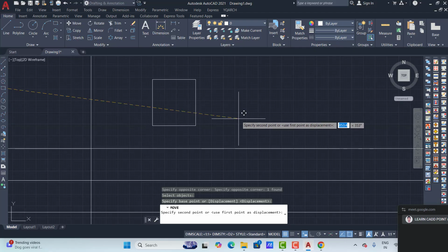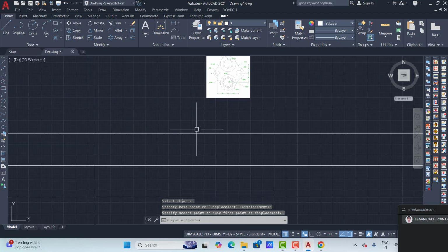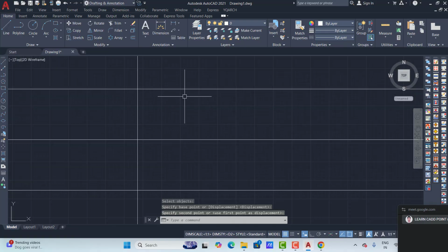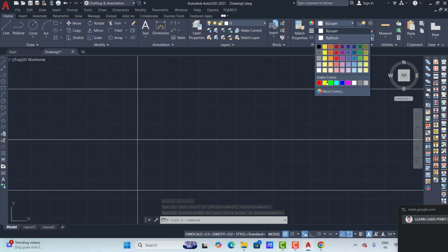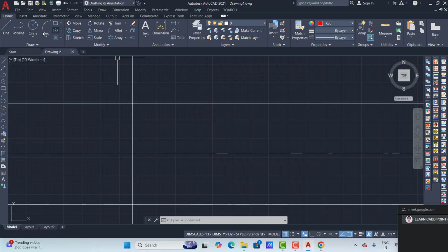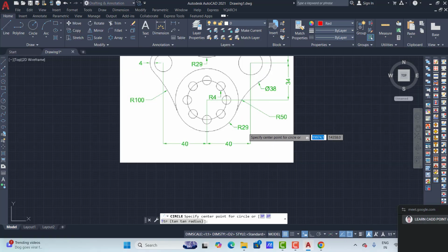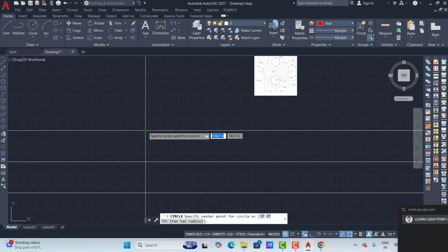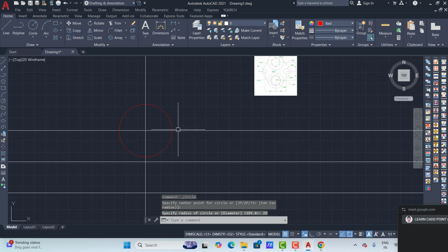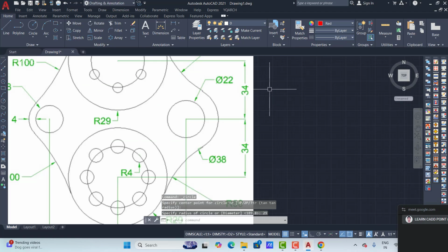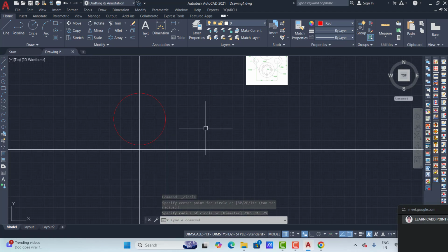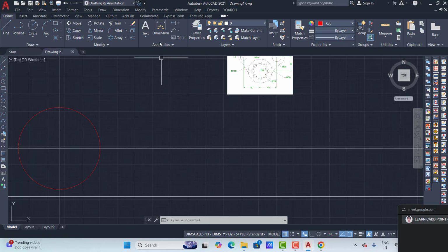So just press control P and here select DWG to PDF. And here we can select paper A3, A4, and here I have a window option. Select window option, just click and click here. And you can check preview one time. So this way coming, it is not exact center. So just you can click here center. If you want black and white, we go here, use monochrome and yes, line. Okay.